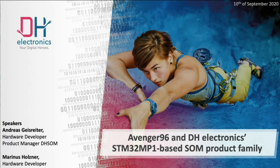And to the Avenger96, there we are using a module from Murata, the 1MW module. This is also pre-certified for FCC, but the module is not directly on our SOM. So in that case, you have a pre-certification for the module from Murata, but if you're using this module in your own mainboard, you have to do the certification by yourself because it's not on the SOM in that case. Okay, so Chris, I think that's all to this question. All right, thank you, Andreas.